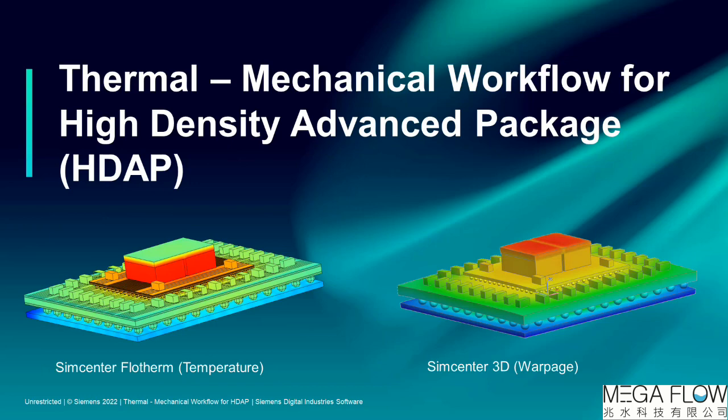In this presentation, I will go over a thermomechanical workflow for a high-density advanced package. So here, Simcenter Flotherm is used to solve for the temperatures, and then that data is brought into Simcenter 3D for structural analysis where warpage and creep are analyzed.